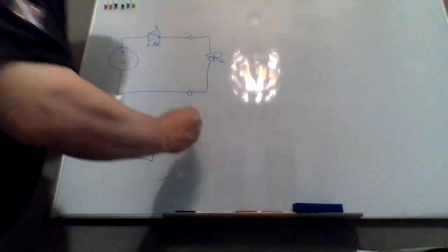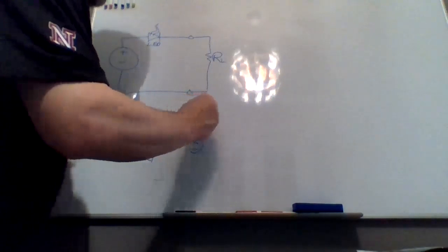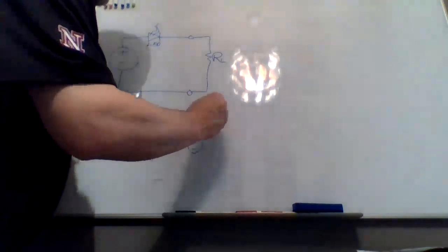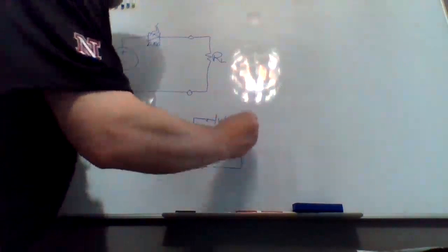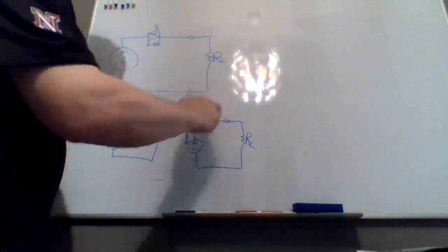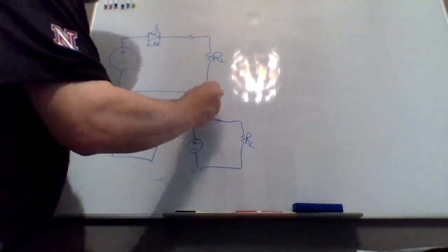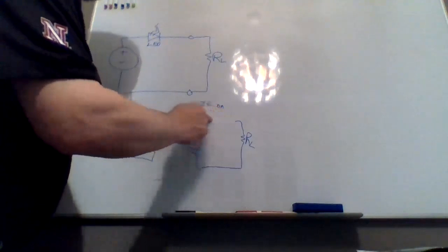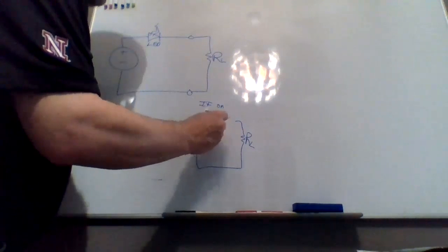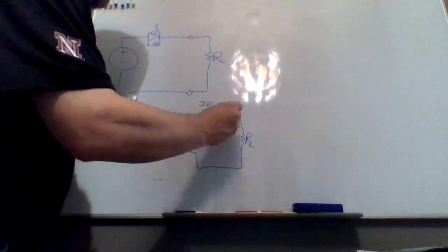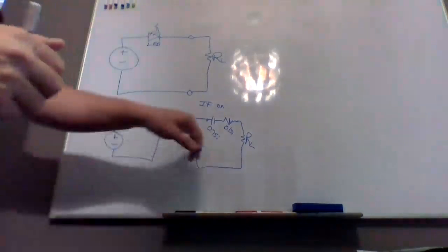Or they might have it where they say, well, it's got a forward bias to it, okay? Such that if it is on, you replace it with a little battery, low resistor, in an ideal diode, that battery goes to 0, and that resistor goes to 0 if it's on. If it's not on, or if it's not ideal, then you put that in, and remember it's usually like 0.7 for silicon or something like that. And you put a resistor in here, and it's usually really small resistance, like 0.1 ohms or something like that, but you still put it in. So that's a real one.